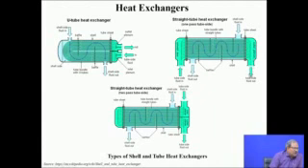They are not recycled once again, which is what you see in a two-pass tube side. So what happens in a two-pass tube side? You have the inlet plenum through which the liquid goes, comes through the tubes, comes to this side, and then will travel once again, through these tubes to the other side. So this is a separator which does not allow these two streams to mix.